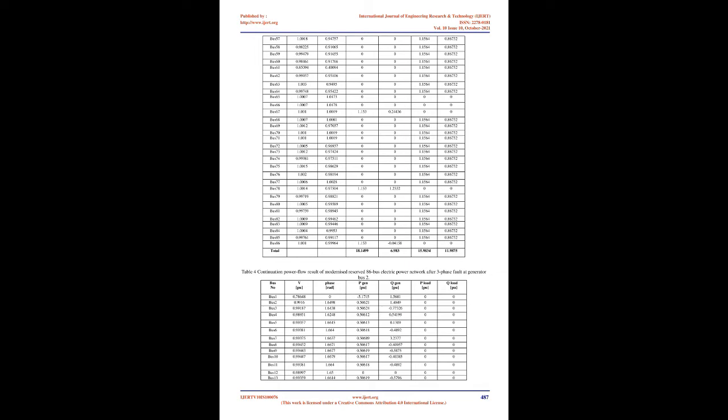Continuation power flow allows the load voltage to be computed even when the power flow Jacobian matrix is singular. The complete P-V curve, including the critical, nose, point and the lower part of the curve, can be drawn using continuation power flow. The complete PV curves of the network are drawn using the MATLAB Simulink Power System Analysis Toolbox, PSAT, that uses continuation power flow.